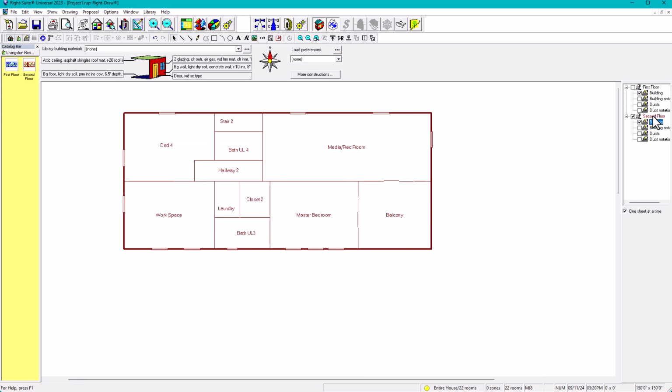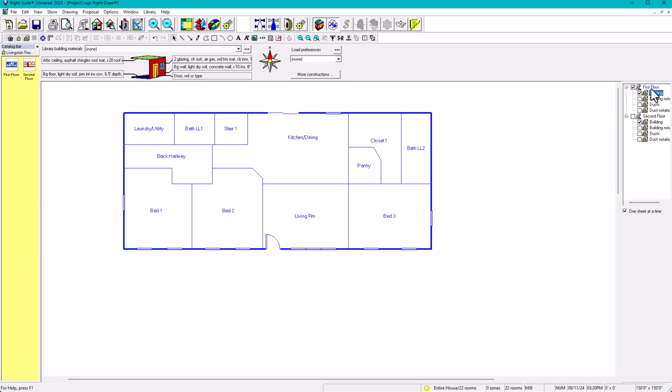You can put 1, no problem. Depending, does it have a basement? No basement. Where are you gonna put the 2 of them or 1 of them, right? In the attic or in a mechanical closet? It's better to put it in a mechanical closet. But now it's a good idea, depending on the square footage of the house, to have 2 systems, right? Even if it's better to have 2 systems, like two units of 2.5 ton each, instead of a 5-ton unit completely, right? So in this case, I know it's more expensive and everything, but it's better.